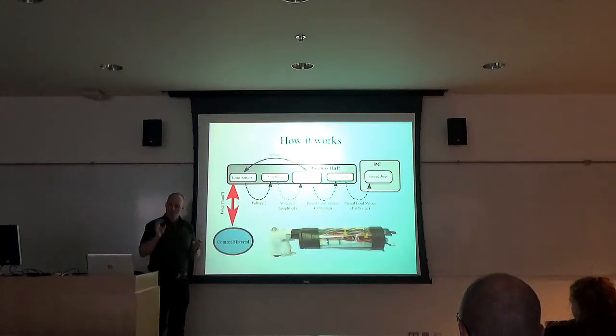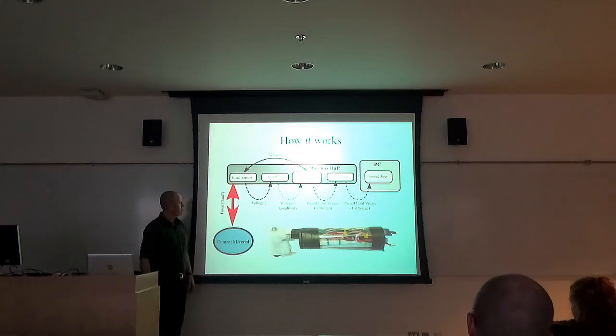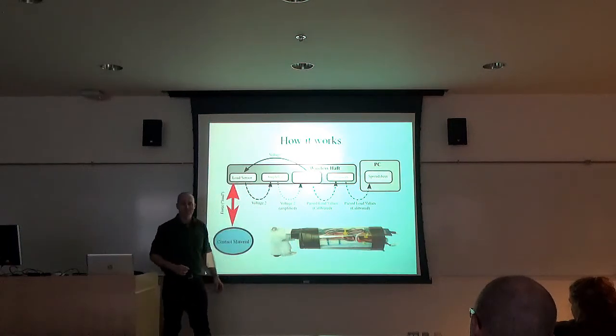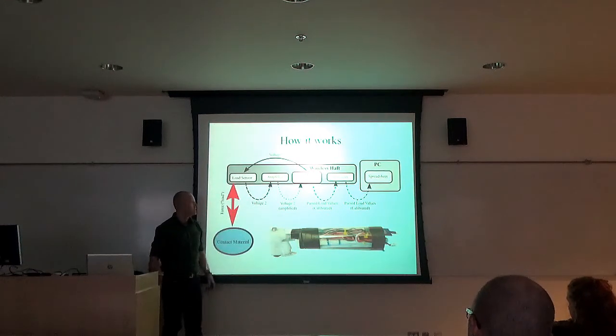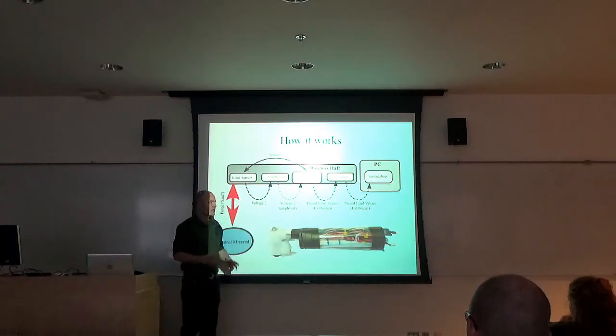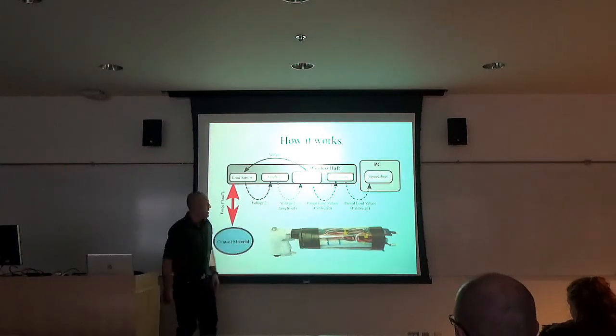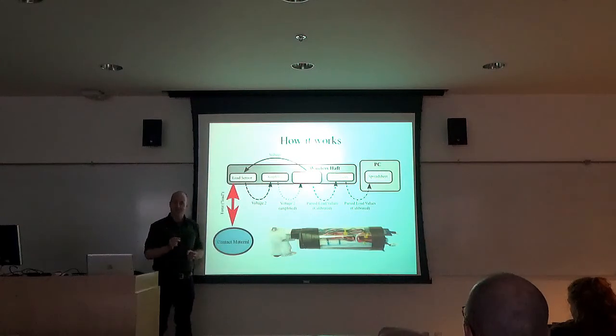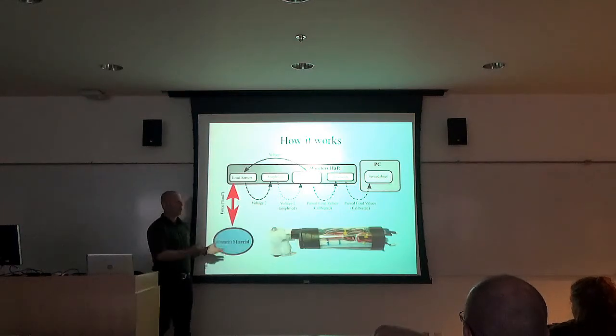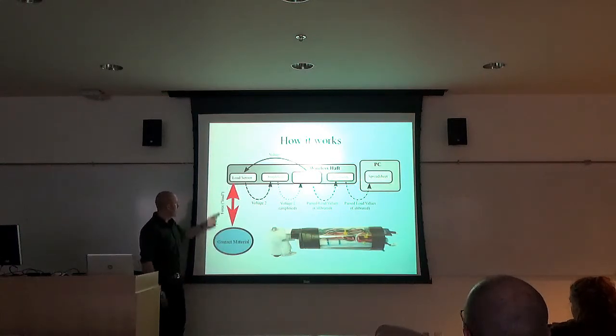But that voltage changes in an extremely tiny way. So from the original, I guess it's 3.3 volt output, it's going to be getting marginally less than that back after this deforms. The amplifier increases that signal so that the Teensy can read it again, and then the Teensy can translate that, based on this basically having been calibrated like you would calibrate any other scale, into something that makes sense, like kilograms or newtons or whatever your flavor of load metric is.